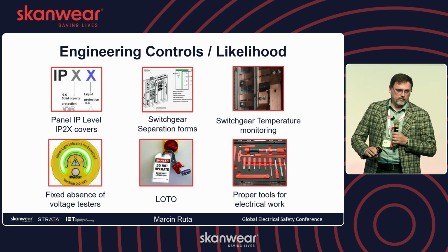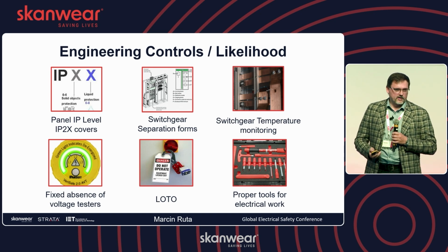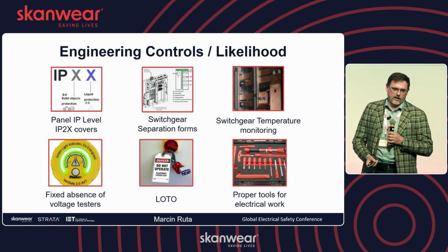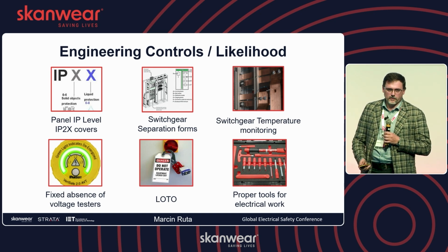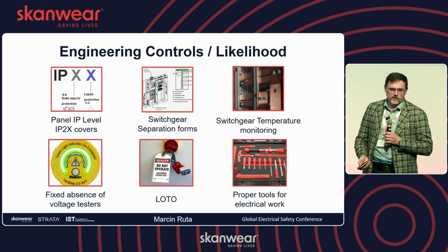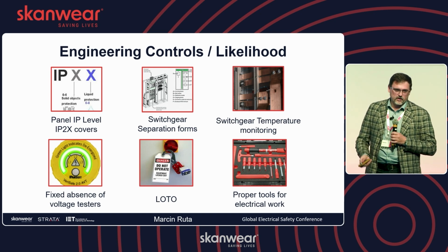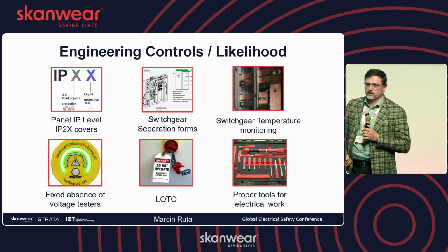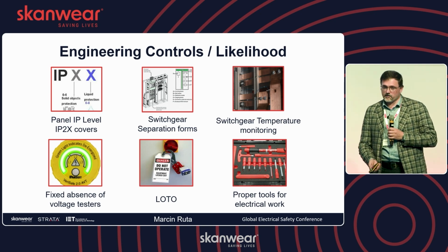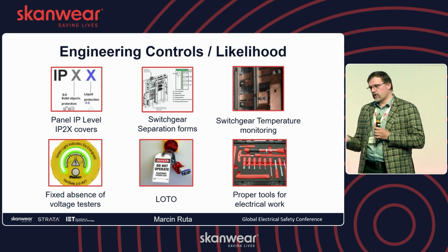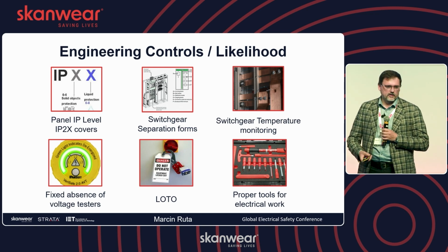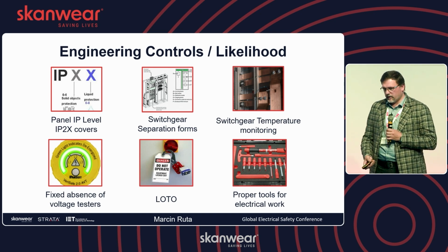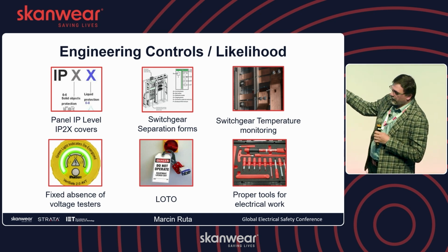Of course, from the engineering perspective, IP level, which sounds like a stupid thing, but IP level is very important from an operation and maintenance perspective. If you have it wrong, there will be a constant hazard in your electrical system, and a lot of violations will pop up on the site. Switchgear separation forms, again, the same thing. If someone doesn't think about it at the very beginning of the design, later it's very hard to change. Switchgear temperature monitoring, like the fixed one, is an interesting thing that has been coming for years now, but it's not very common to have. Also, a fixed absence of voltage tester.